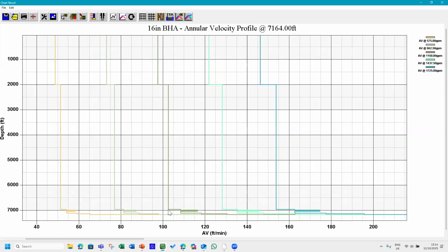There's a lot of things you can do to optimize it. You can optimize the fluid. You can optimize the ROP. We are trying to aim for high ROPs. But here, ROP doesn't matter anymore because it's just the speed of the fluid. You want that speed to be more than 150 or let's say 200. You don't have that. So what could be the solution for that?